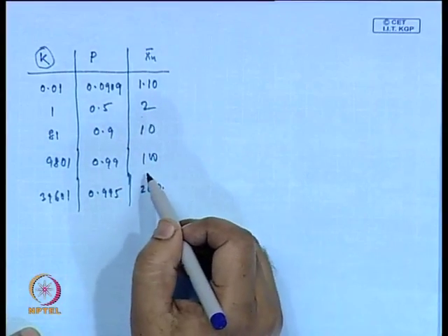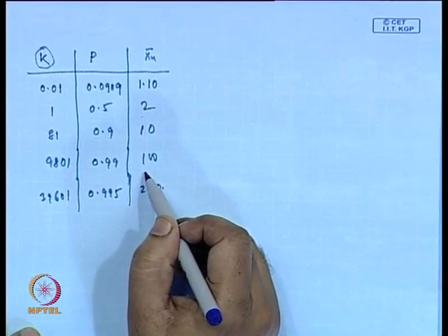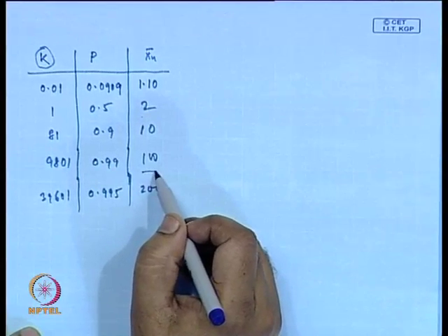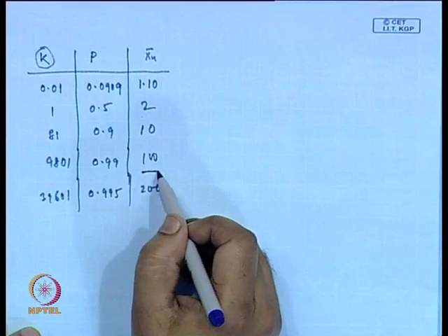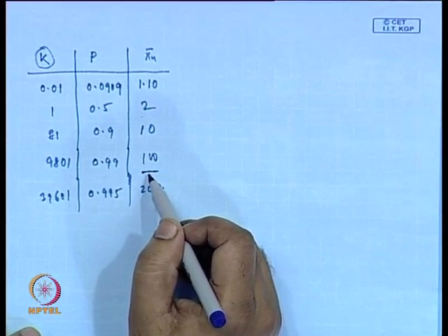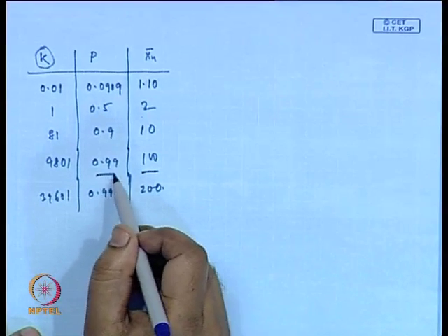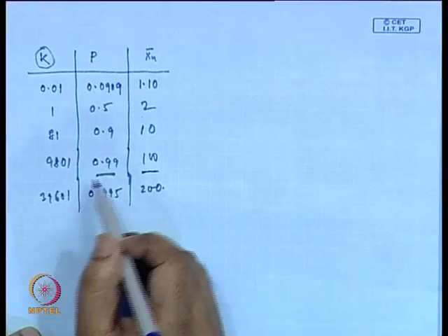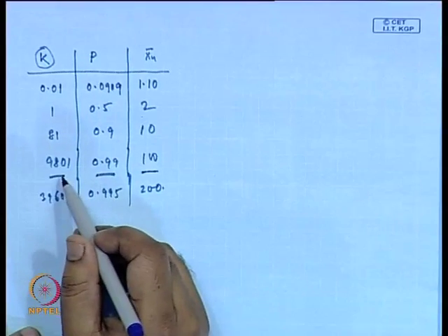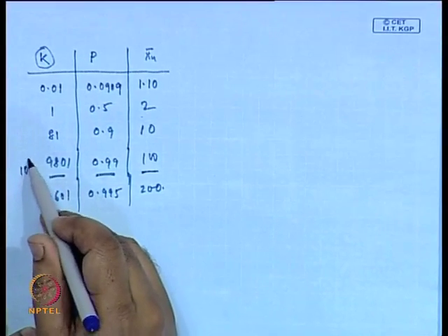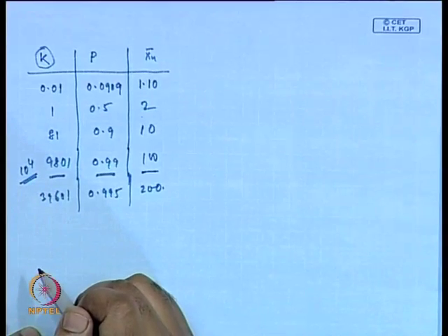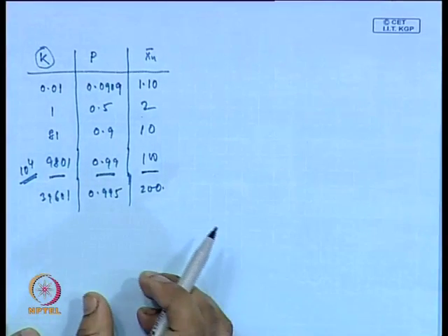If you want to build molecular weight, that means if you want to build a degree of polymerization of 100 in a closed system, then your equilibrium conversion has to be 0.99, which means your K has to be almost of the order of 10 to the power 4. That means, by itself your reaction has to be very highly reactive, so that without removing the byproduct you can get the product.